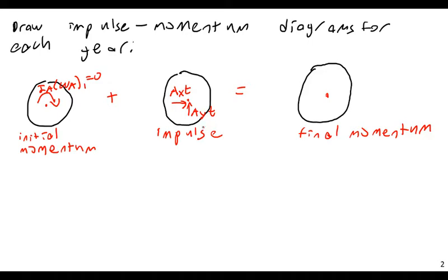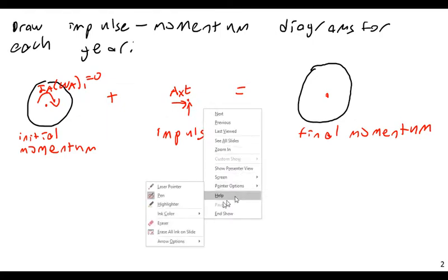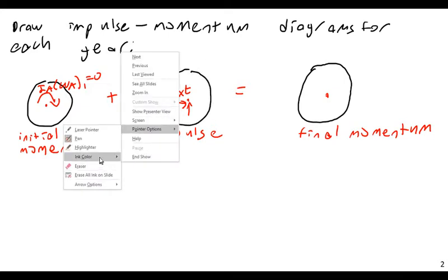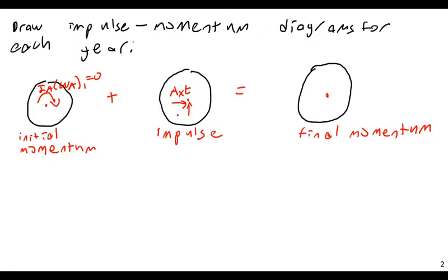However, these don't really contribute to the momentum in the system, since they cannot contribute to the rotation, since they have a moment arm of 0. And again, this is AY times T. And then I need to take into account the tangential force, the contact force between the 2 gears.